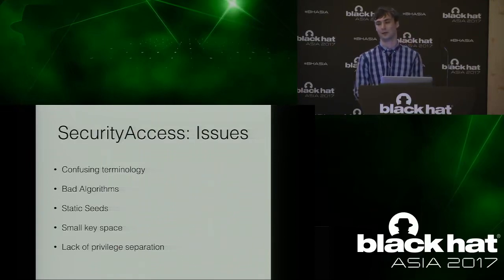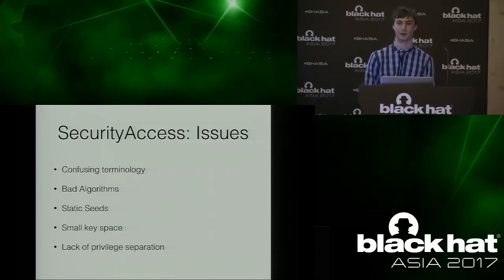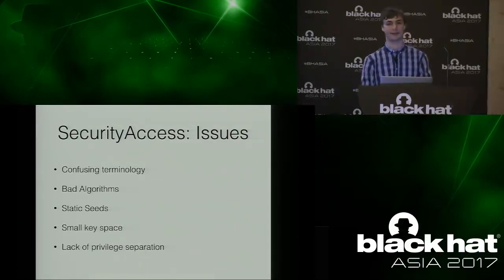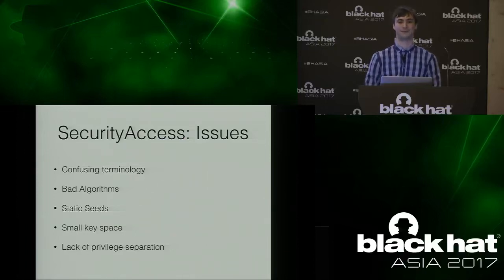So what you do is you pretend to be a car. You plug this tool in, and you say, all right, give me the response for seed 0. Give me the response for seed 1. And you just go all the way up to FFFF. A lot of these tools work offline. They don't have any connection to a backend. So what you end up doing is just creating a map of 65,536 values to a different set. And now you have the whole key space, and you're done. You're in. And that's clearly going to be an issue. If someone can do that, they forever have the algorithm.